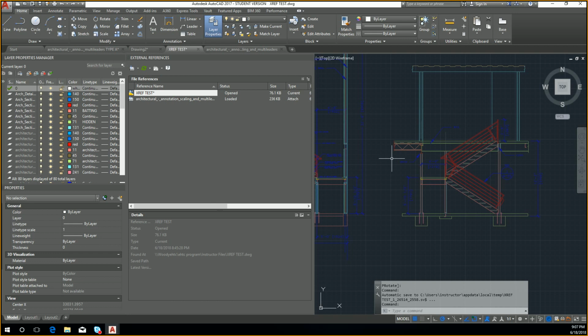That's sort of where it differs, because you cannot explode the external reference. Actually, can we? No, there's no way to explode an external reference. That's where it differs from a block insertion. Block insertion is just for that very reason. You would bring it in, explode it, and do your stuff, and that'd just be a snapshot, right? Or you keep the block living and you redefine it.